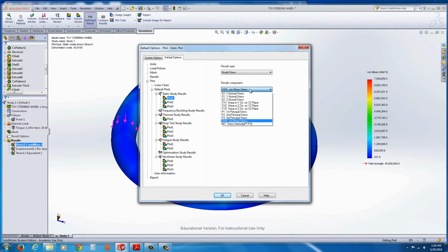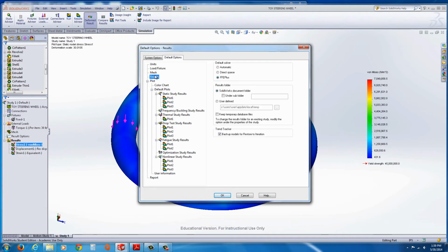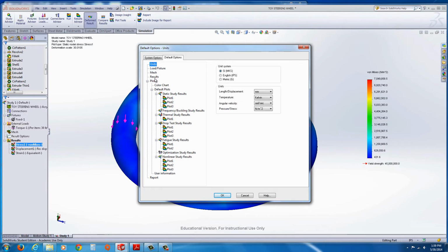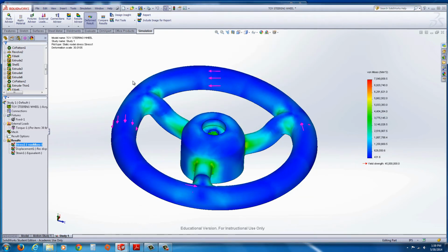plot, we'll set this to, let's see here. Actually, let's see, it would be the, it's eluding me today. Okay, we could set it to English IPS here. And here we go, under pressure stress, just set it to MPa. Hit OK. I know that's a mix and match there, but like I said, the material data sheets are very useful. You could look up the MPa instantly pretty quickly on most things and find it.